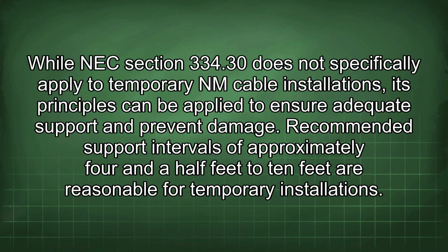While NEC Section 334.30 does not specifically apply to temporary NM cable installations, its principles can be applied to ensure adequate support and prevent damage. Recommended support intervals of approximately 4.5 feet to 10 feet are reasonable for temporary installations.